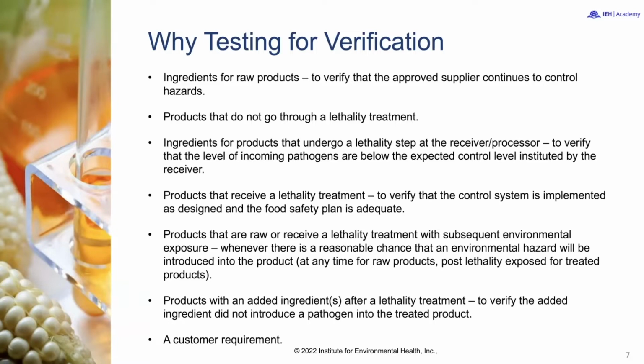Nobody in the canned food industry pulls a few cans off the line and tests them for something like Clostridium botulinum. That's a case where we have such robust thermal processes and ability to control those processes in that industry that what we do for verification testing there might be nothing more than a small set-aside program to verify commercial sterility.